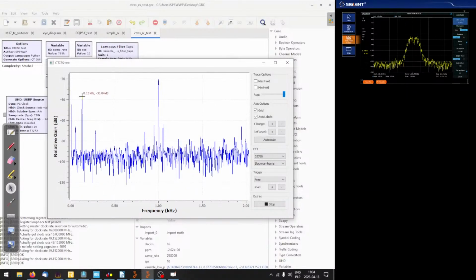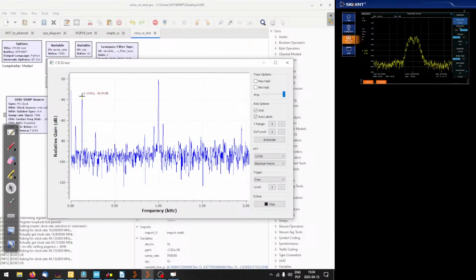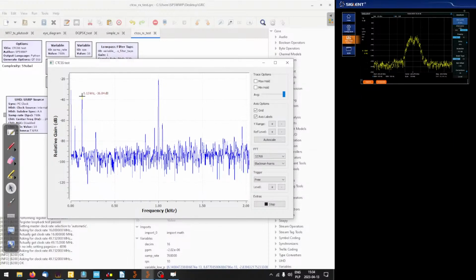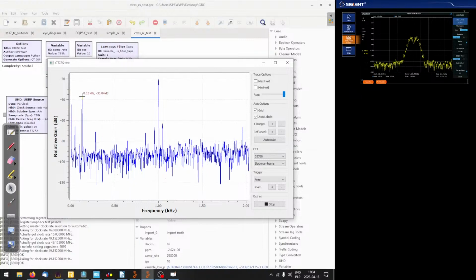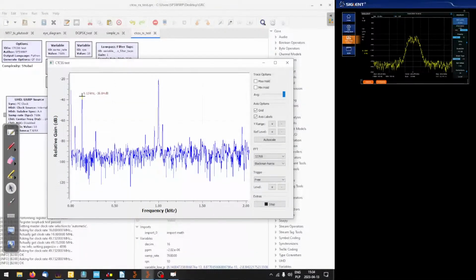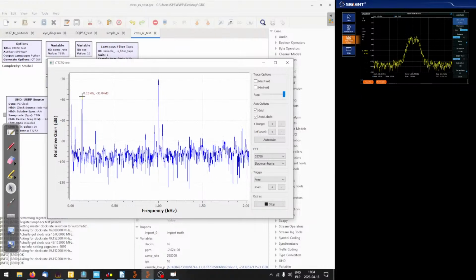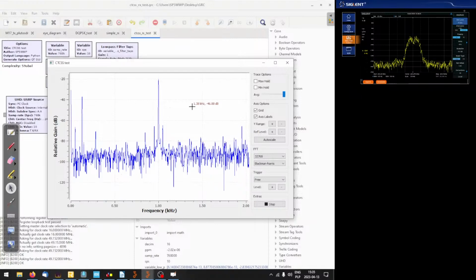By changing into a value close to the one on the TX, like, can you explain this to me? What I'm going to do is change the CTCSS tone in the OpenHT to 205.3, if I remember correctly.